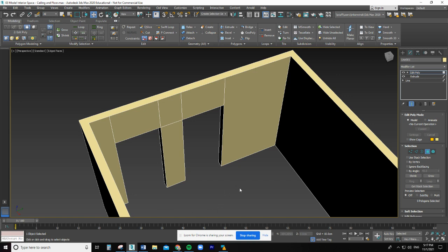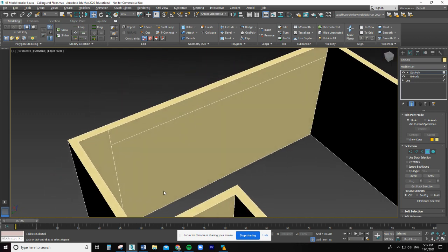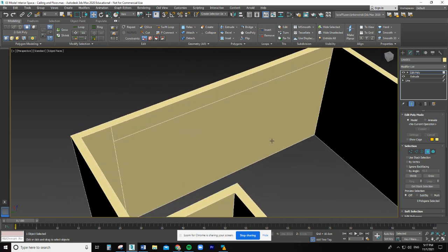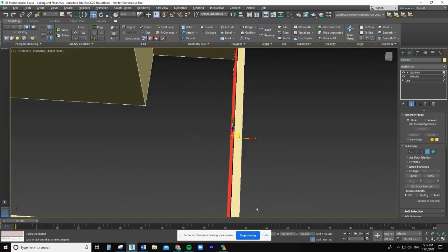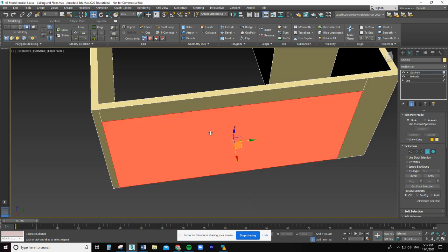Okay, so now I'm going to swing around and let's do the same thing here for our large wall-sized picture window. I'm still in the polygon selection tool here. So I'm going to select 1, rotate around, and before I select, I'm going to hold the control key down and select.